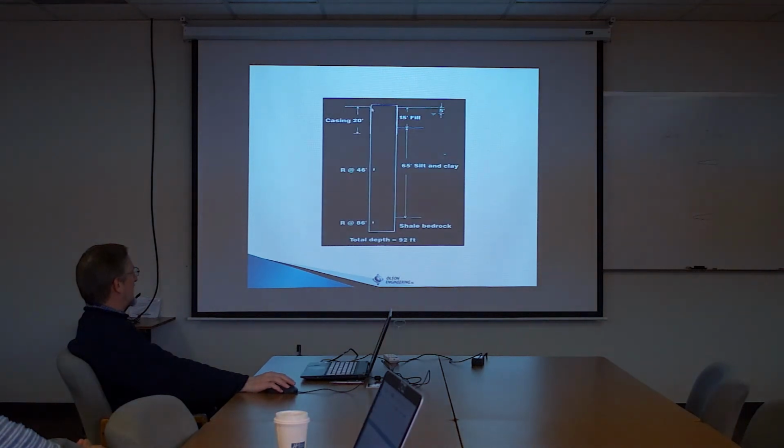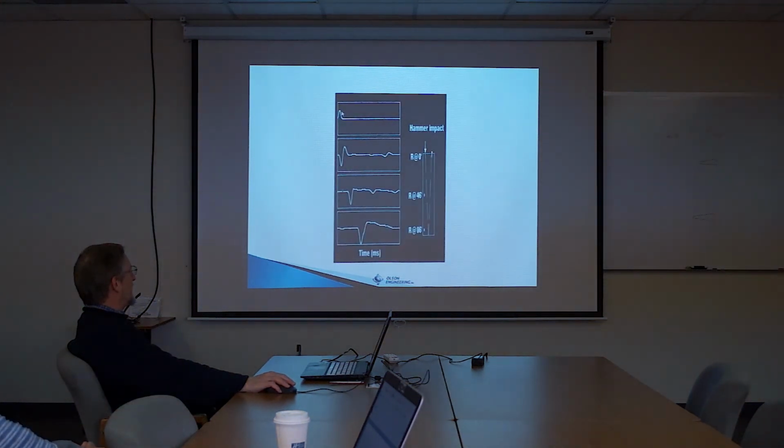So this shaft had, and these are very old slides, 25 years old, a geophone buried at 46 feet and another receiver at 86 feet. The bottom is at 92. It shows the waveforms from these various channels that were all collected from the same hammer impact.